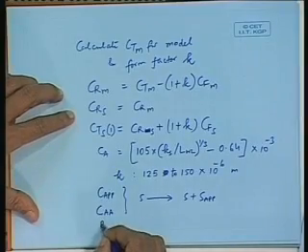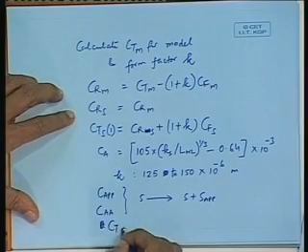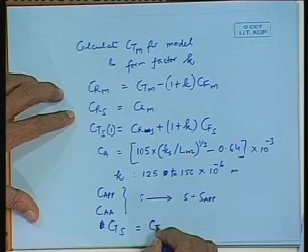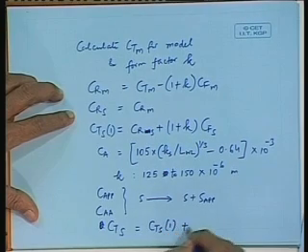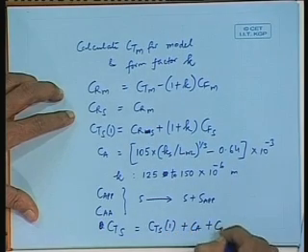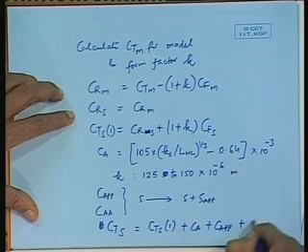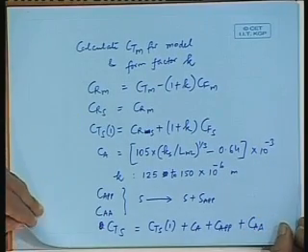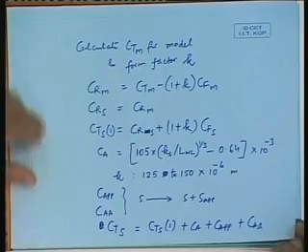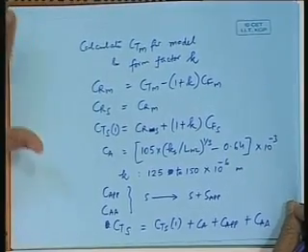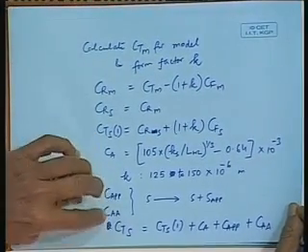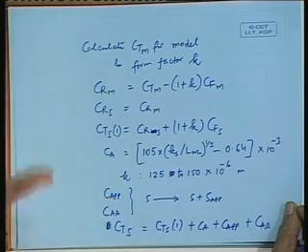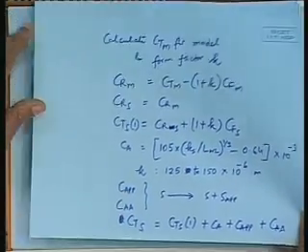Then you get CTS equal to CTS1 plus CA plus CAPP plus CAA. All this will give you the actual ship resistance. The CAA will depend on what sort of trial condition you want to do.